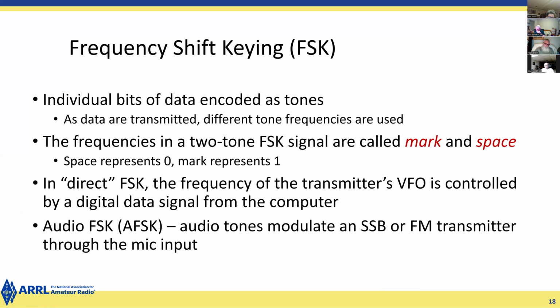And for audio frequency shift keying or AFSK, which is much more common these days, audio tones are used to modulate a single sideband or FM transmitter through the mic input, or more commonly these days through the auxiliary audio input. Most fairly modern HF transceivers have an aux audio input on the back panel, which you can use so that you're not plugging and unplugging the microphone.